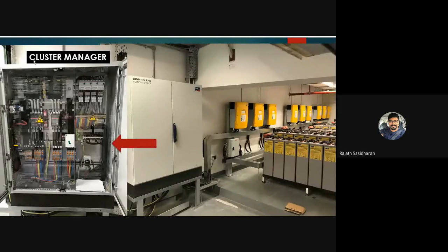There are some contactors. There is this part, but it's not clear in the photograph. That's the brain. That's where the circuit board goes. All the IC chips and the programmable computer. It's a computer itself. It is designed with an algorithm on charging, discharging, and battery management, equalization, so float, absorption, whatever it is designed with these kind of capabilities. And these multi-cluster managers will instruct the battery inverters to perform their operation.